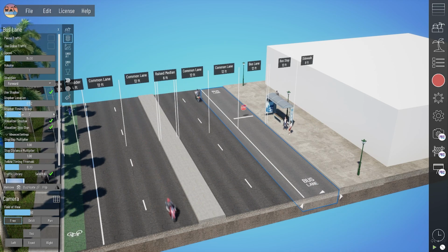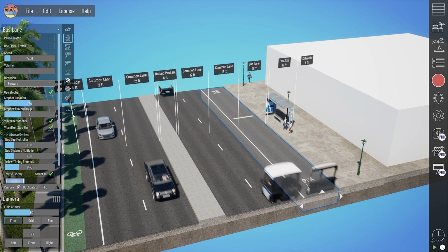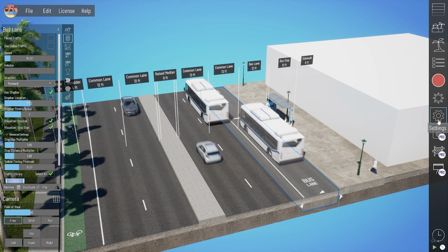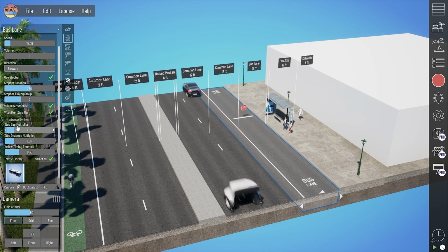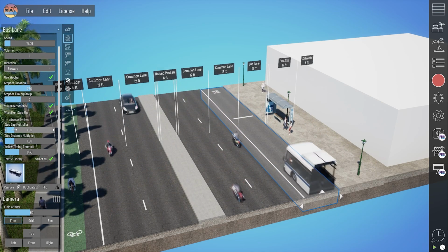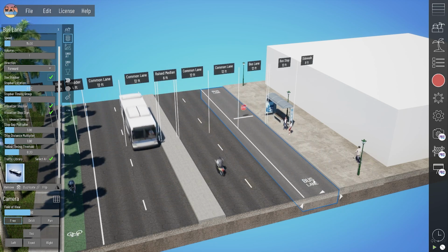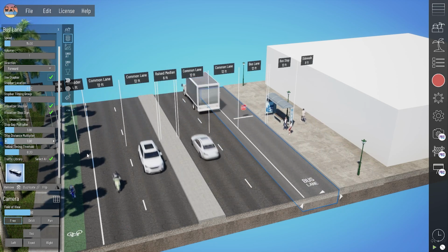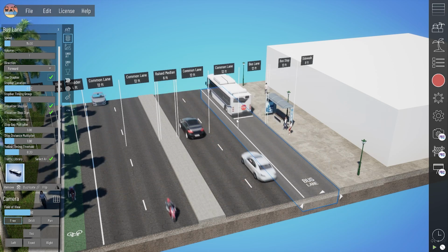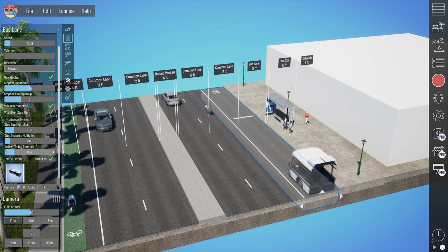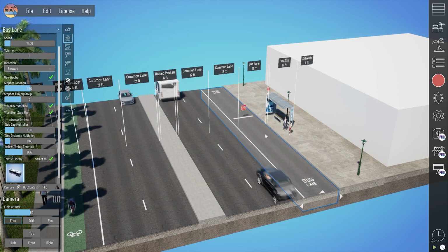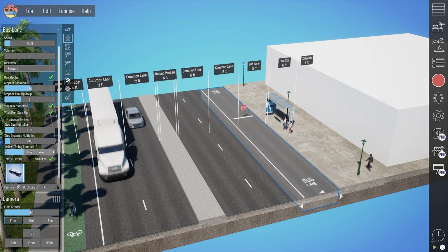We also have a stop bar timing group. So there are 4 different groups that we can adjust that timing to in a set of stages that I'll show you later in our global settings. There are also some of these advanced settings. We're still working through these and may update these in future patches, but for now you can play with these if you want to see traffic behaving differently, like coming to a stop slower or faster, or leaving more space between the vehicle and either the stop bar or vehicles in front of it.